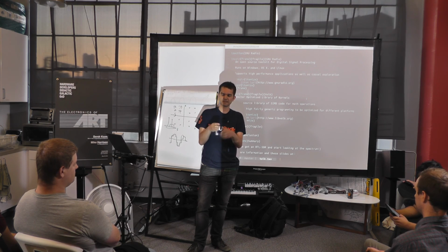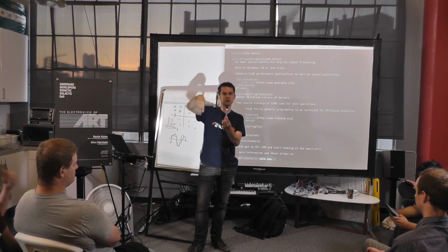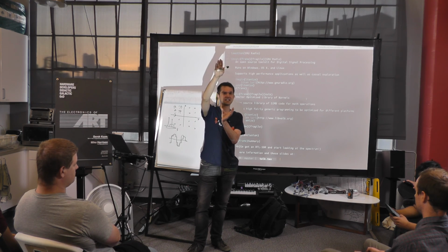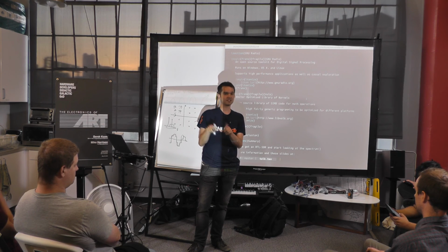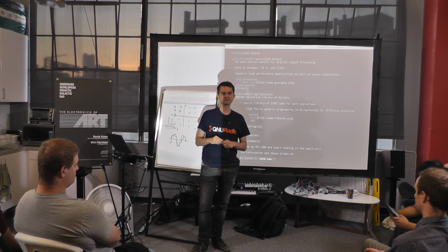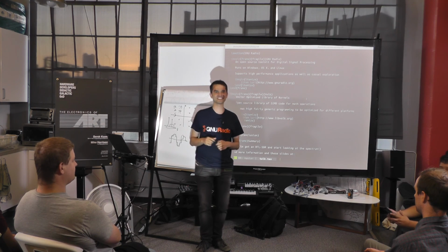A dipole radiates in basically a donut shape around it. If you have a satellite dish, you have this kind of pear shape looking up straight along the axis of the dish. For a 12-foot dish at 10 gigahertz, that's less than a degree wide. It's about 0.4 degrees, which almost perfectly matches the moon. So you have to steer it very carefully.